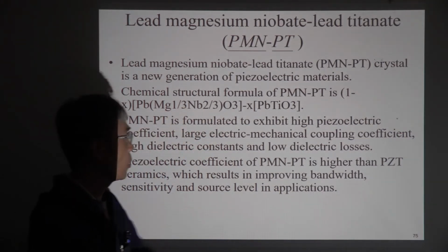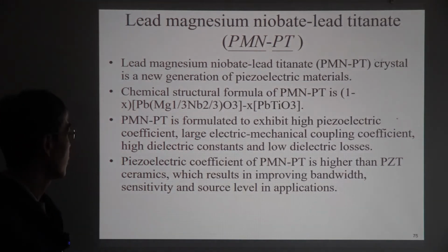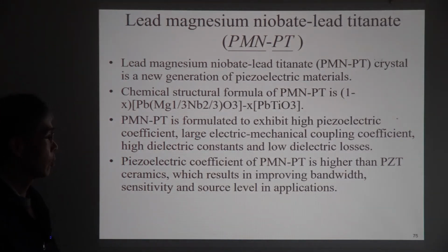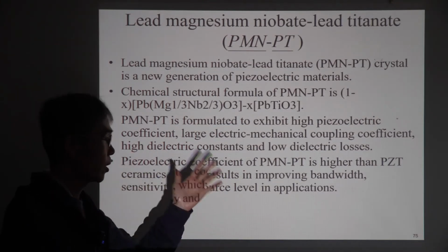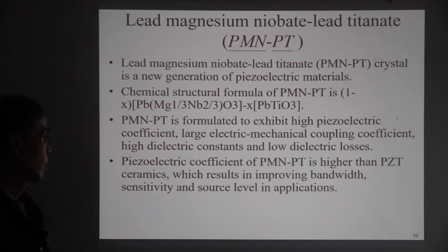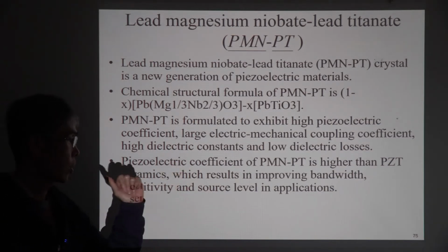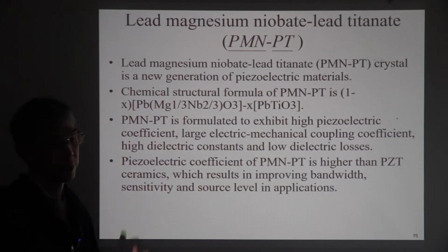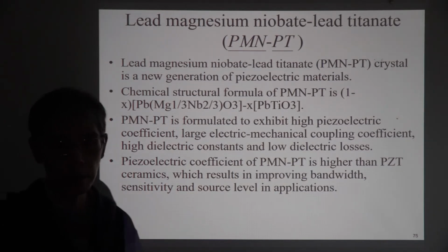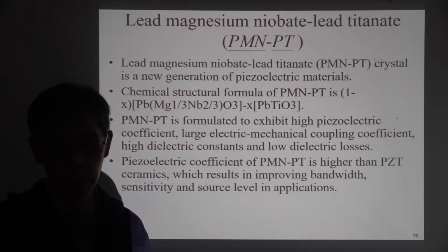So this material has a high piezoelectric coefficient and a large electromechanical coupling coefficient and high dielectric constants and low dielectric losses. Perfect, right? Its piezoelectric coefficient is higher than PZT. So it can improve the bandwidth, sensitivity, and the source level. So it's a much better material.